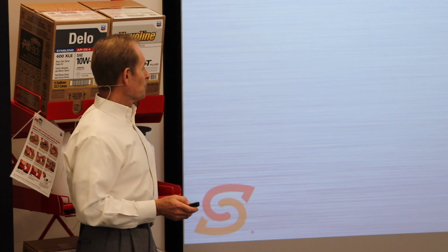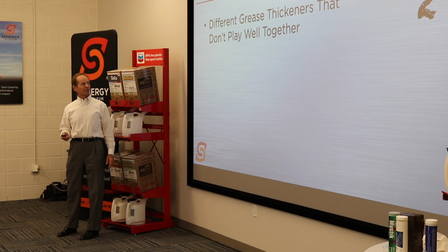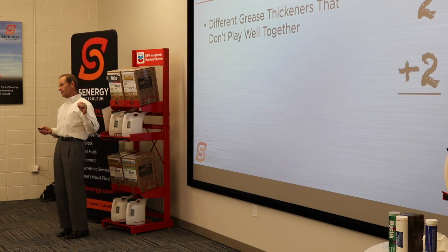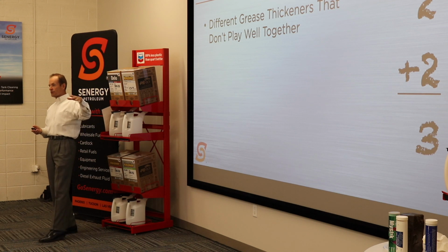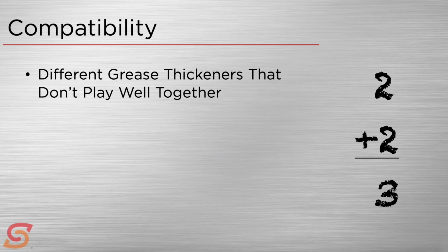All right. Okay, let's go into, as they say, the third half of my presentation. We'll talk a little bit about compatibility, because you may have heard of compatibility and compatibility issues. So this is another takeaway. I hope you go away with learning a little bit about this. And hopefully what you won't take away is more confusion than you already have. So we'll see. Okay, so compatibility is when you have different grease thickeners that don't play well together. The base oils between two different greases are fine together. The additives between two different greases would be fine together. It's all about the thickeners and them having a problem playing together.